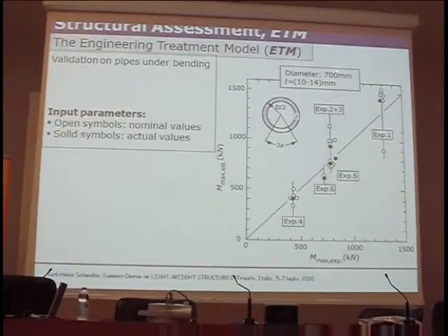The diameter was not too bad, but I did the analysis with and without pipe ovalization, because when you bend a pipe, it ovalizes a bit, so you did it with and without. You see it's quite a bit of work. You do the R-curve analysis, you have the R-curve on your millimeter paper, and you have to vary the applied bending force, and you overshoot, you undershoot, and in the end you do an interpolation.